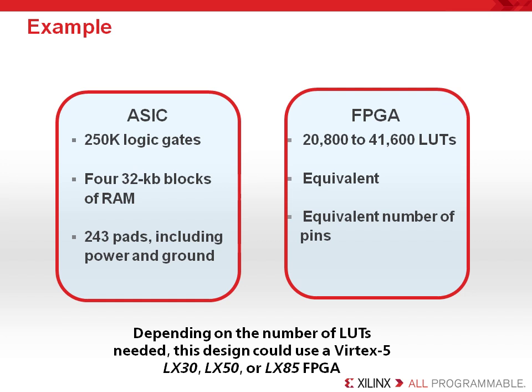However, most customers like to design around the 80% device utilization level. This makes it easier to meet your timing needs. If the design was running at low speed, say less than 150 MHz, you might be able to pack the design at higher device utilization. You should also keep in mind that no modifications have been made to the design to help it run at high speed, so further design changes will probably need to be made. We'll talk more about design changes in a little bit.